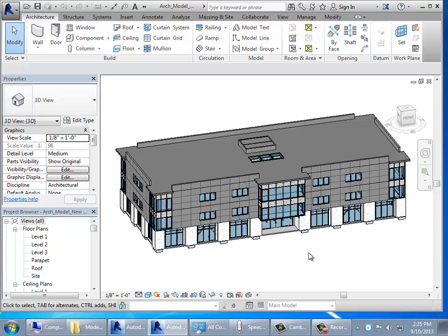There are actually ways to get things backwards compatible a little bit. In fact, I think later in the class is going to have you experiment with transferring some other kind of BIM modeling systems. So there's some formats like IFC where you can actually save your Revit model out in that common format and bring it back into the older version. You lose some information. There's always some sort of loss along the way, but you're never completely down a well. There's always some way to kind of get it out there, and that's one thing we're here to help you with.